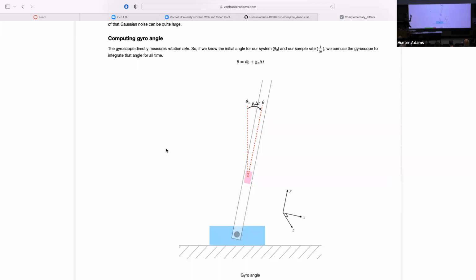And then each time into this interrupt, I'm going to gather a gyroscope measurement. In particular, I care about one axis of that gyroscope measurement. If this is the z-axis, we care about GZ, rotation rate in this direction. And we say, well, I am just going to integrate the output of my gyroscope to maintain an estimate of my current angle. I know where I started. I know the angle that I started.